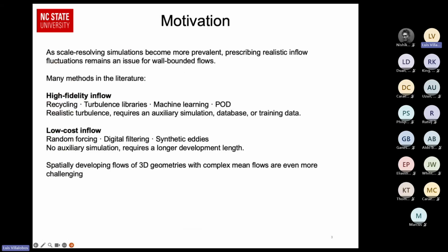So our motivation for this work is that as scale resolving simulations become more and more prominent, the problem of enforcing realistic inflow fluctuations to start turbulence in the simulation remains an issue. There are many methods that have been tried in the literature, and many work to varying degrees for certain cases. In general, you have your high fidelity type inflows like recycling and rescaling, using turbulence libraries, and some more exotic techniques that use machine learning or POD.